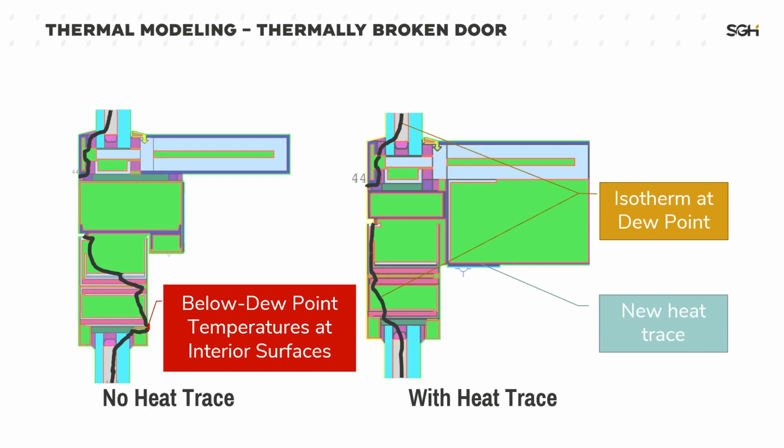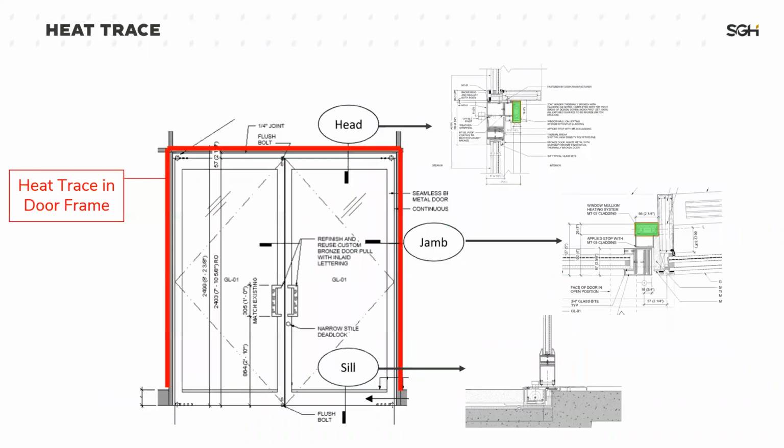Yeah, so there are different things we can do to heat the inboard surfaces. Sometimes we'll have a warm air wash, which I mentioned before, which is just like squirting warm air near the windows to kind of dry them off, basically. In this case, I didn't get into the electrical design. We don't really do that at SGH, but it's basically a wire with a current running through it, and so it's warm.